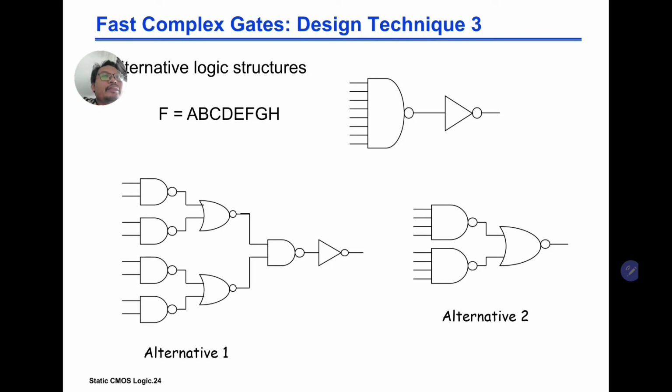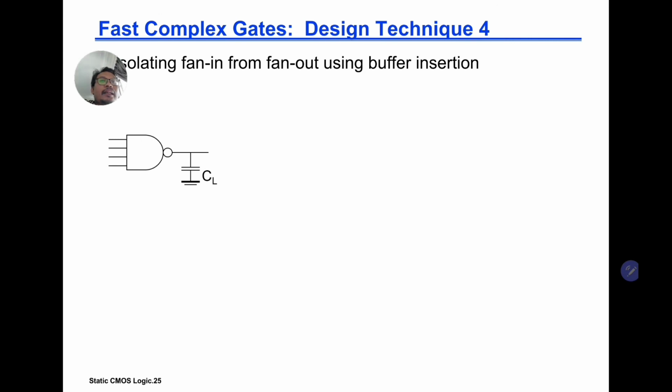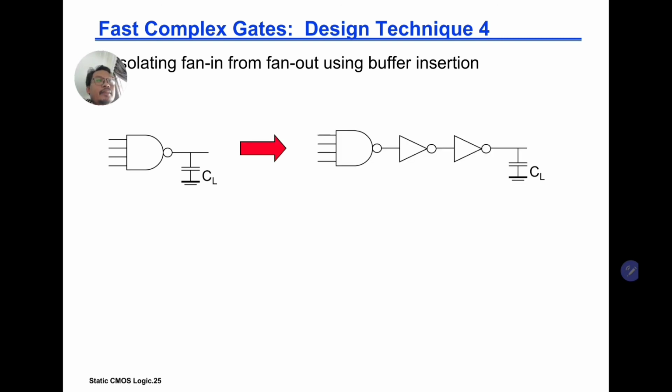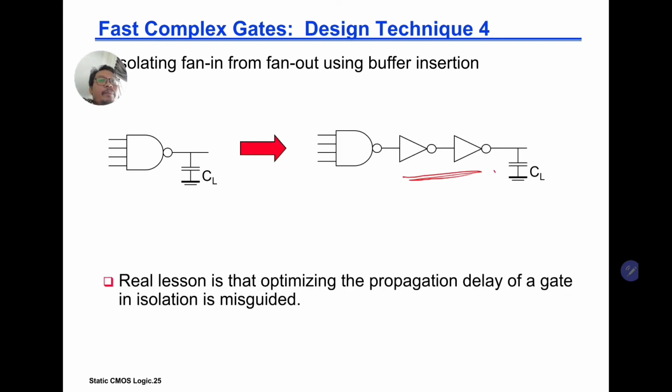Design technique number 3, logic restructuring. Let's say you need a 10-input NAND. You can break it up and it's more efficient, something like this. We will look into more detail later on in the logical effort timing optimization chapter. Next, isolating fan-in from fan-out using buffer insertion. You can insert some buffers here.